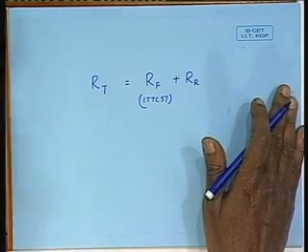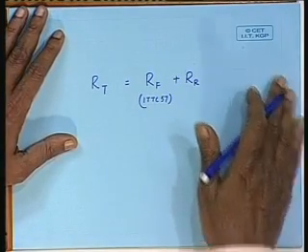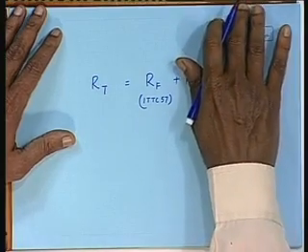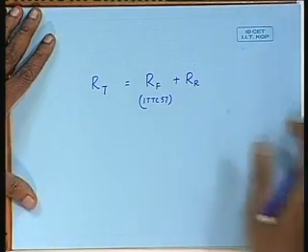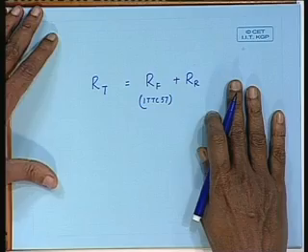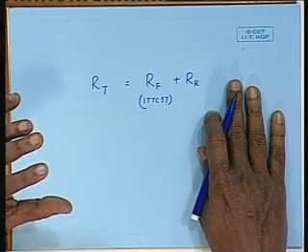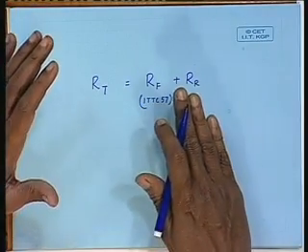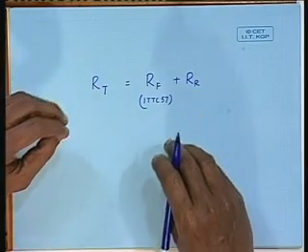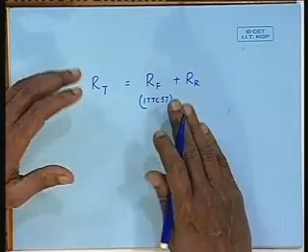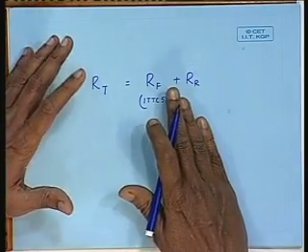If we go back further than that, in our first class we had divided the various components of resistance, which we will again see in the next lecture. You will recall that we had said that the two-dimensional frictional resistance alone is not the total component of viscous resistance. There would be some other components of viscous resistance, which may be small in quantity, but they are there and they are not included in this ITTC 57 line.